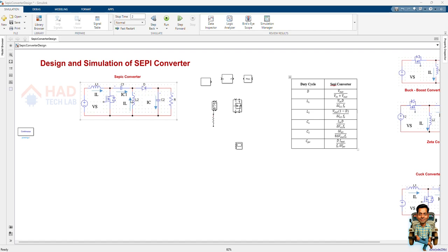A circuit is called single-ended when the switching device MOSFET is connected to the ground on one side instead of using a bridge or push-pull arrangement. In a SEPIC, the MOSFET is referenced to the ground. The inductor L1 is also referenced to the ground. When the switch is on, there is only one active switch. So the converter has a single-ended switching structure.